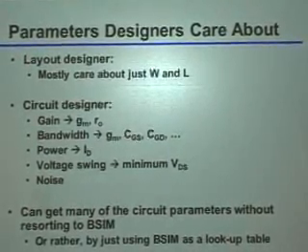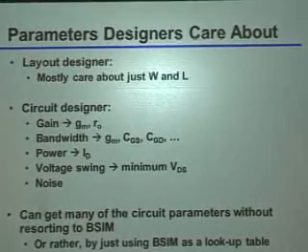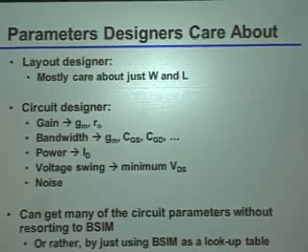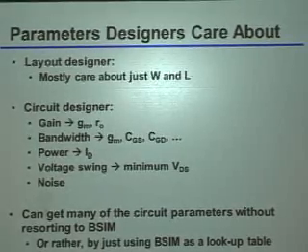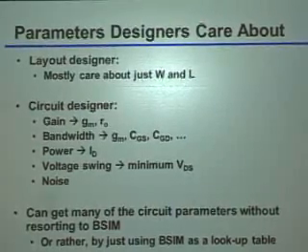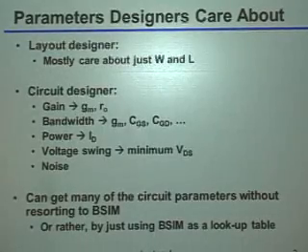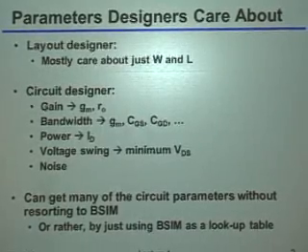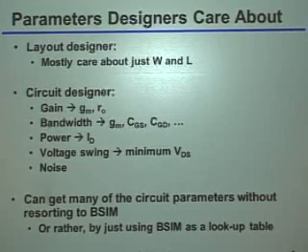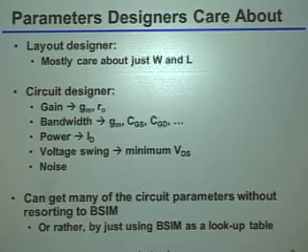But typically as a circuit designer, the width and the length in and of themselves are not what you care about. What you actually care about are circuit level parameters. As an example, you care about how much gain you're going to get, how much bandwidth your circuit is supposed to have, how much power it's going to dissipate, and how much voltage swing you can get out of an amplifier. But the width and length don't intrinsically tell you something about those parameters.